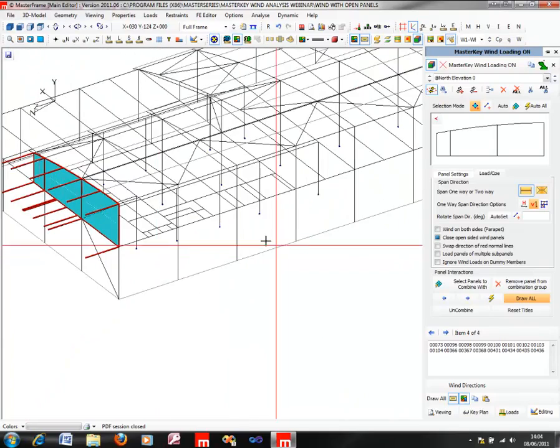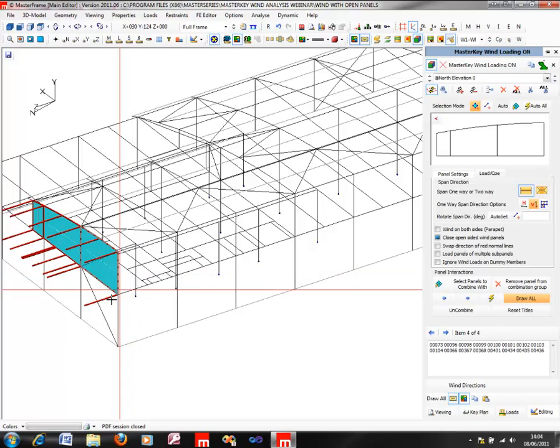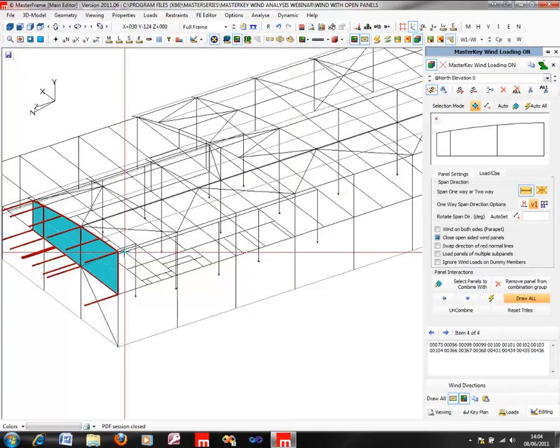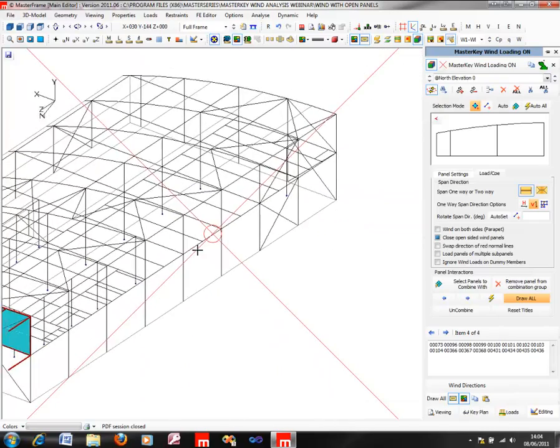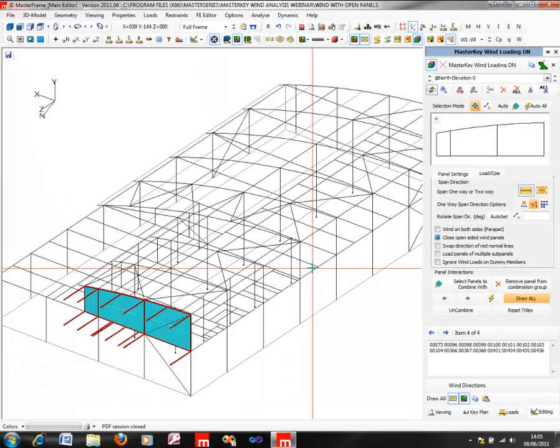Now that zoning, that banding, I would continue actually around, so that the splitting up would continue around the other side of the structure and all the way around the entire structure, so that this surface would be separate from this surface. Where you have that inset story type of arrangement, we would recommend that you split your panels up in that fashion.